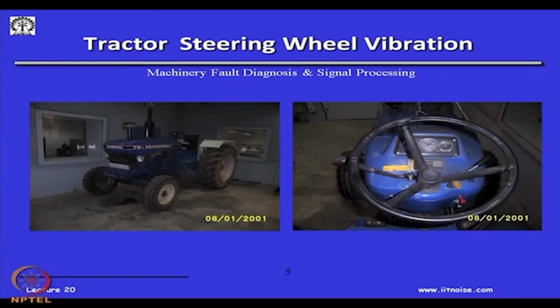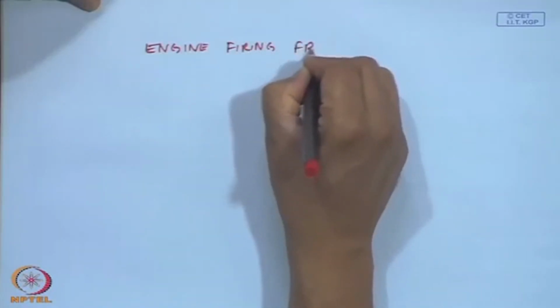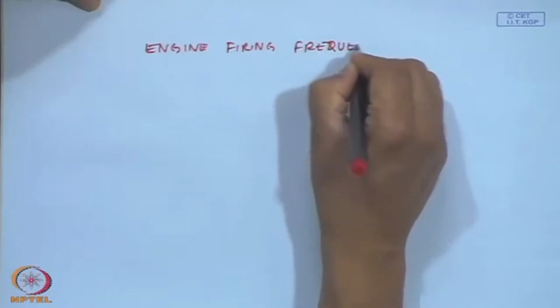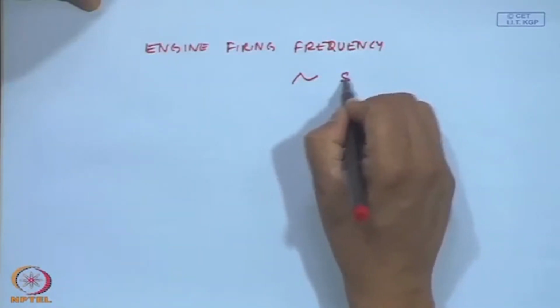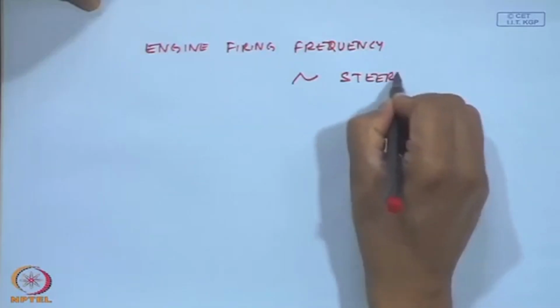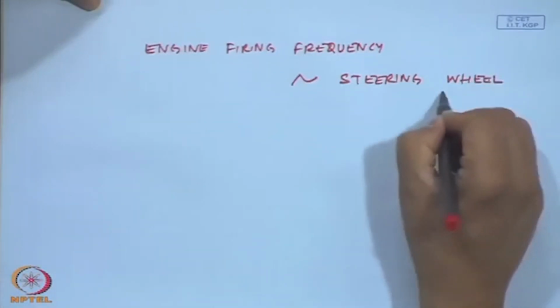So, in this particular case, what happened is that the firing frequency generated by the engine was almost close to the steering wheel resonance.